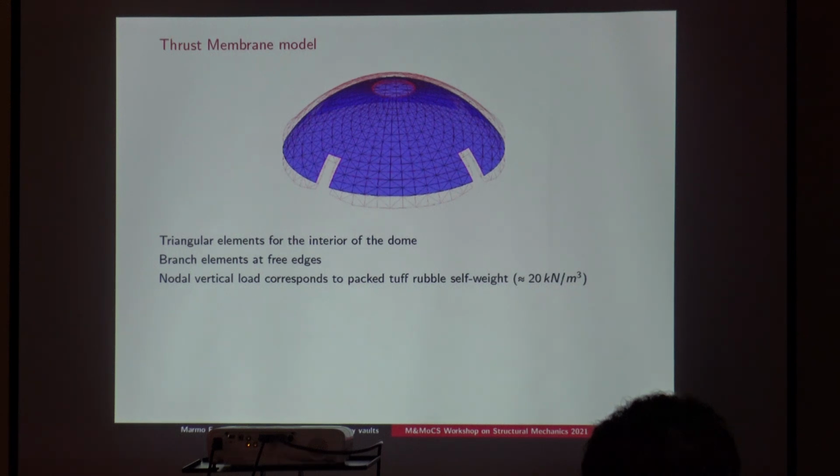And so usually you should look at the stereotomy, if you can, or consider different topologies of the model, and since you are within the safe theorem of limit analysis, you can choose the one that maximizes the multiplier of the applied load. Because it is the safe theorem, you are reaching the limit from below, so you can maximize everything.